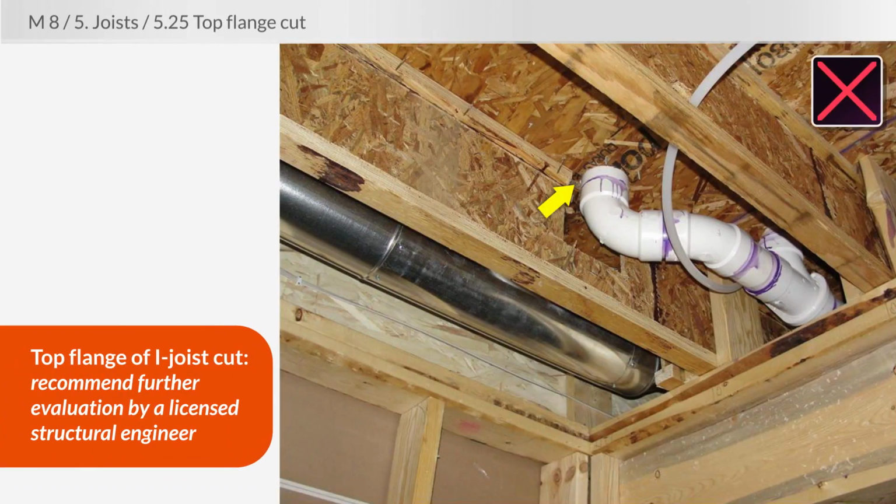Once again, we have the top flange of an I-joist cut. In the I-joist industry, this cut is so common it has a name. It's known as a bucket cut. When you see the bucket cut, you recommend further evaluation by a licensed structural engineer.